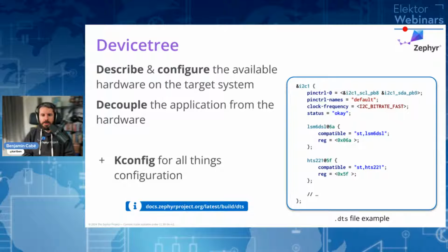The only thing you want to do is use an off-the-shelf Arduino board, or an off-the-shelf ESP32 dev kit, and that's it. That's your device. But in many cases, when you're building an IoT product, you're effectively building your own PCB. You might get inspiration from an existing developer kit, but you're going to replace some peripherals by others, some sensors by others, because you're having trouble sourcing them because, hey, silicon shortage.